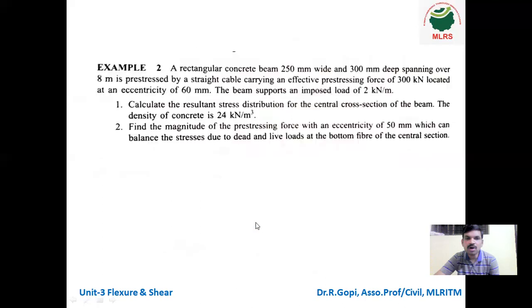Okay. So you can see the second question: find the magnitude of the prestressing force with an eccentricity of 50 mm. So here you can ask one question: sir, the prestressing force is already given as 300 kilonewton, why are they asking for the prestressing force again? So this 300 kilonewton prestressing force is for 60 mm eccentricity. Okay, so understand that one.